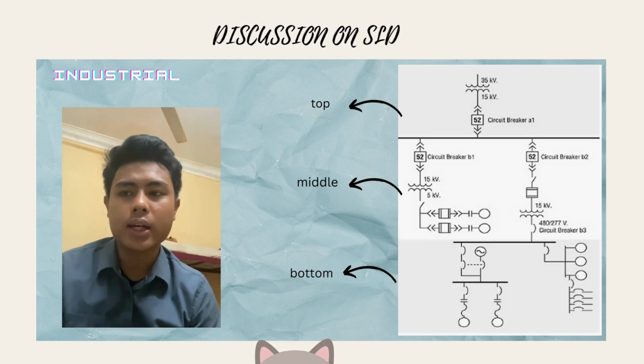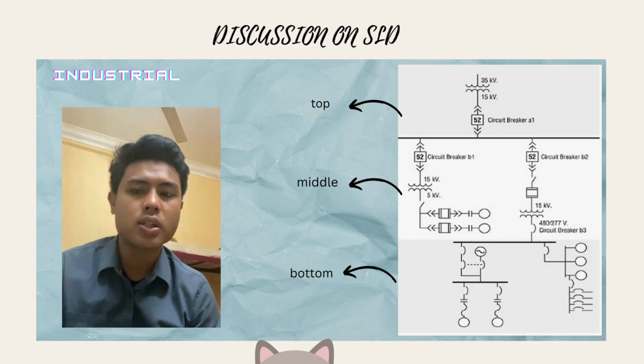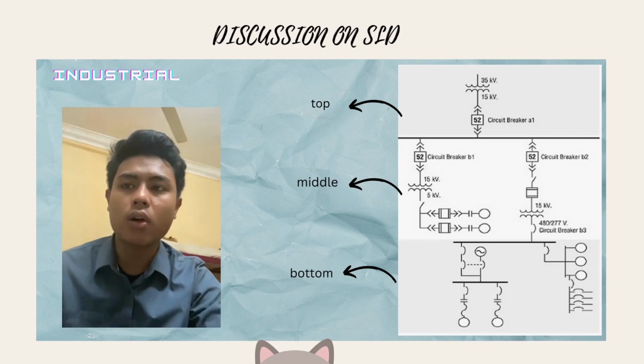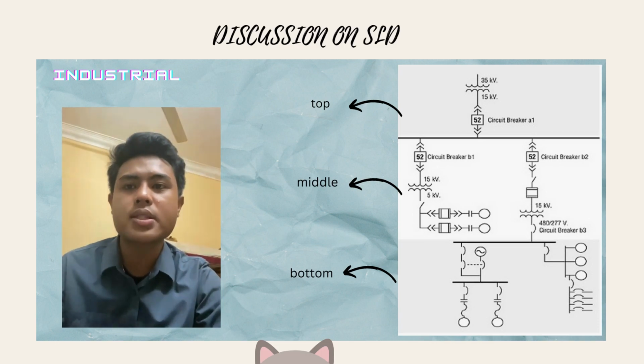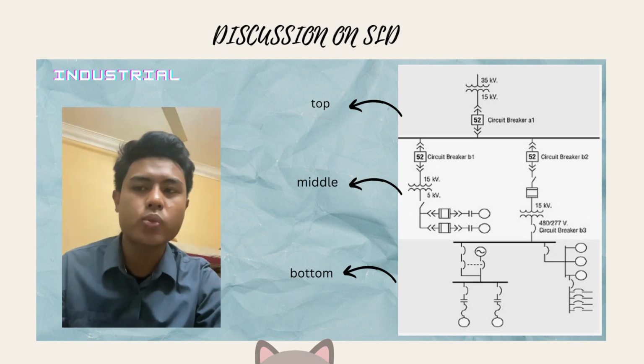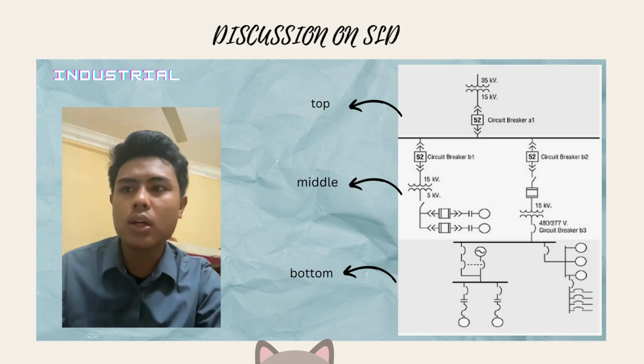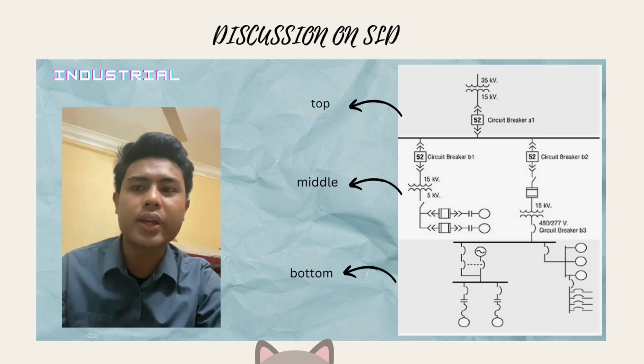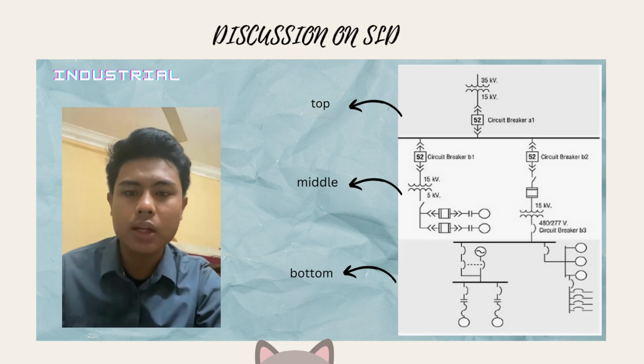The equipment isolated under the transformer connects using the disconnect switch and is in the two medium voltage motor starters. The second drawout circuit breaker is coupled to a step-down transformer and a fuse disconnect switch. Due to the voltage being stepped down again to 600 volts or less, all equipment below the transformer is now regarded as low voltage equipment.